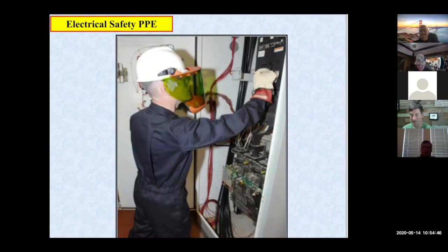And you go down to, you got rubber gloves that are insulators, and you got canvas gloves that are over the rubber, and the canvas protects the rubber. If you're dealing in a panel and you've got that thing open, you got wires going everywhere, you know it's hot, and you're poking around in there with your finger, you ought to at least have the rubber gloves on.